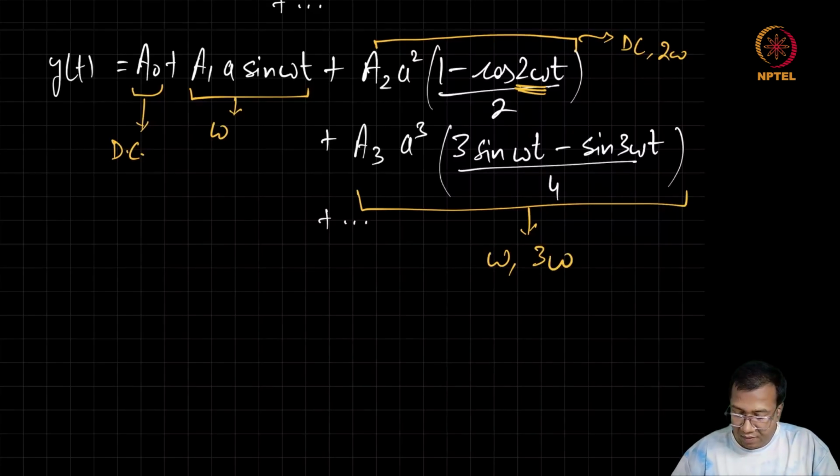So very easily we can see that as the order of the nonlinearity increases, the number of harmonics which you are going to get also increases. So the basic idea is, with the help of this nonlinear term, or such a nonlinear network, we can take an input frequency at omega and generate frequencies which are different from omega.